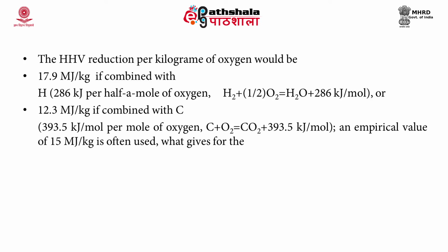That is, if it is combined with hydrogen, H2 plus half O2 gives H2O plus 286 kilojoule per mole. So, using this, the reduction per kilogram of oxygen is 17.9, while carbon plus oxygen producing carbon dioxide plus 393.5 kilojoule per mole will give 12.3 megajoule per kilogram.